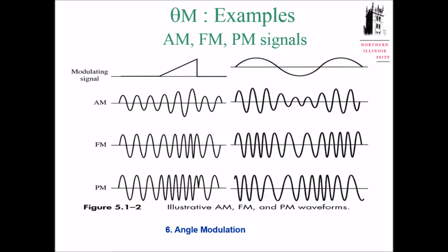So if you change your frequency, your phase is definitely also changing, right? So we cannot fix it. You can fix the initial phase, but you cannot freeze the entire phase of the signal. So your phase is continuously changing. Notice there, the frequency is changing and sometimes the phase is changing, because we have a very abrupt change in your message.